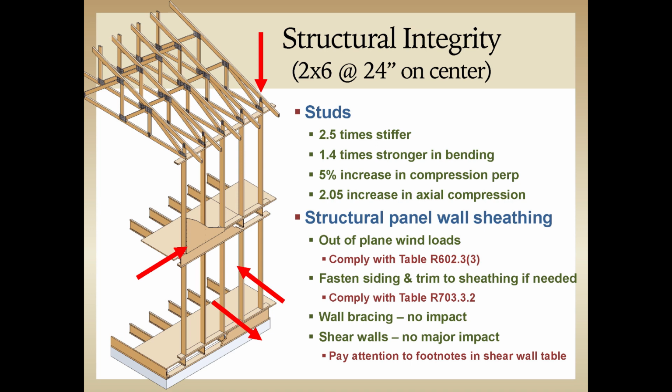And what we found in the field is when you go from 2x4 studs at 16 inches on center to 2x6s at 24, the walls actually look stronger. Now, we have had feedback that interior non-load bearing walls that are 2x4s at 24 inches, so you space your non-load bearing 2x4s out to 24, which does happen in the field, that does look weak. And for this reason, we recommend leaving all 2x4 walls, even non-load bearing ones, at 16 inches on center just to overcome this homeowner perception.